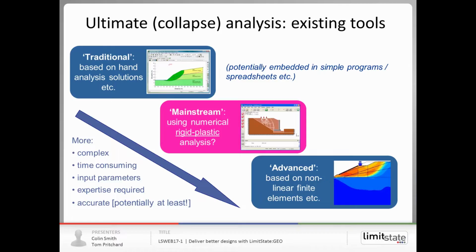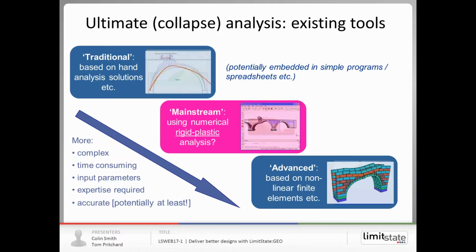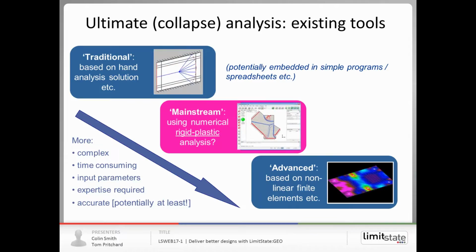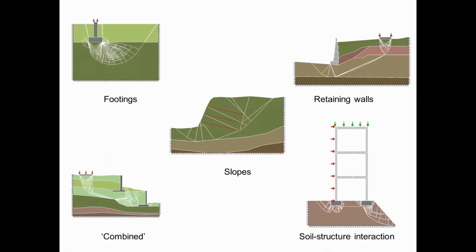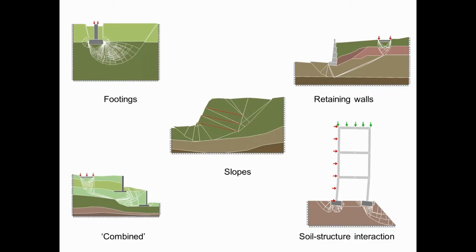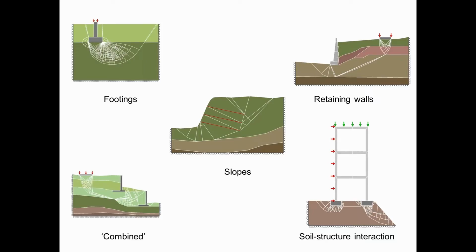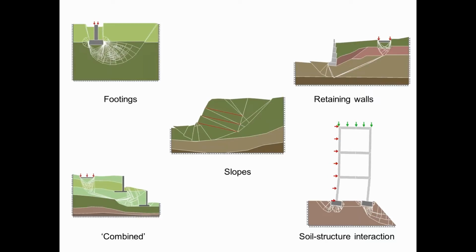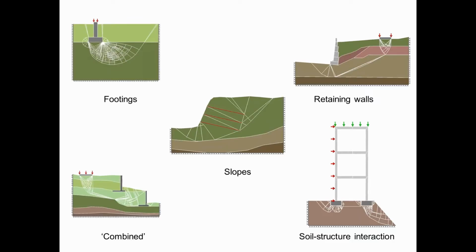And we can take this approach of geotechnical engineering and the same approach with arch bridge analysis, concrete slab analysis, and so on. Such an approach allows the software to determine the collapse state for any problem geometry, so we're able to model slopes, footings, retaining walls, structural elements, soil reinforcement, as illustrated in some of these animations.